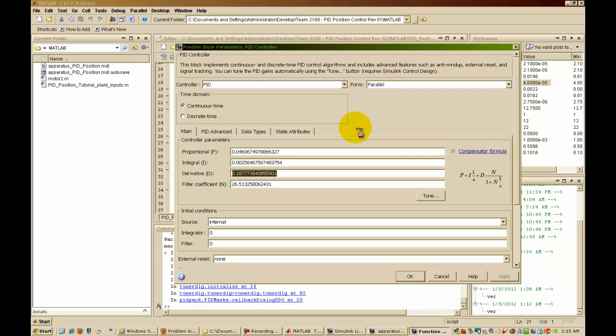So please go ahead and email me and let me know that you're using it and tell me what your experience is. However, if you're using another PID controller, be aware that no two PID controllers are the same because of the various ways that you can implement the PID algorithm. You have a parallel form, an ideal form, a series form, and then you have all these other advanced features. So you may run into issues where the response you get from Matlab Simulink when you put those P, I, and D gains into your other controller, you may observe an awful response.